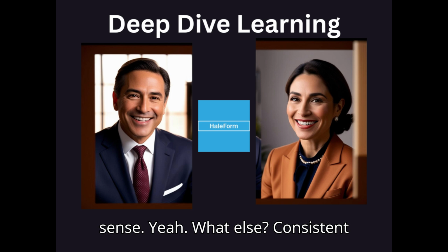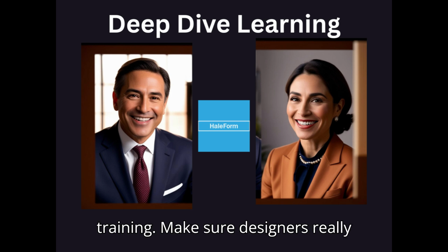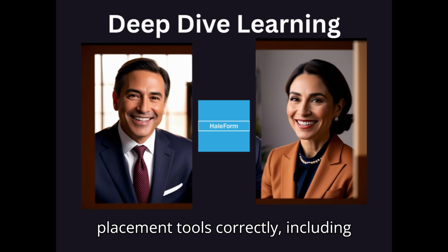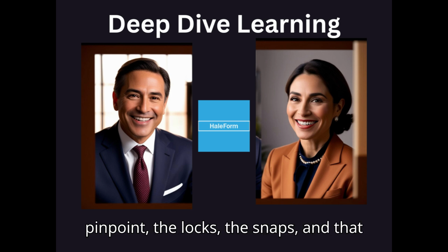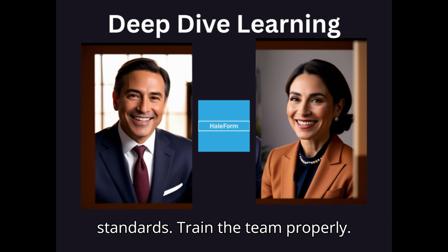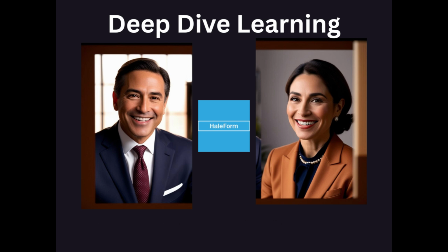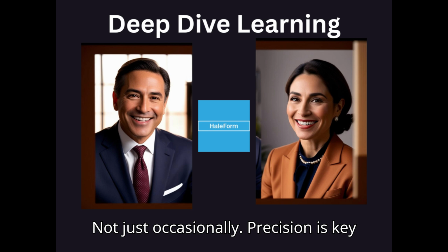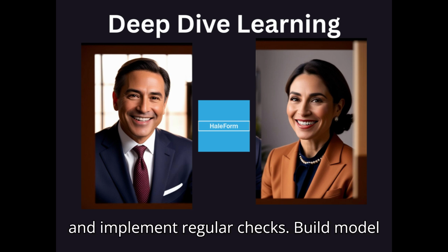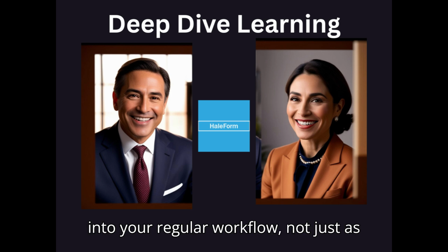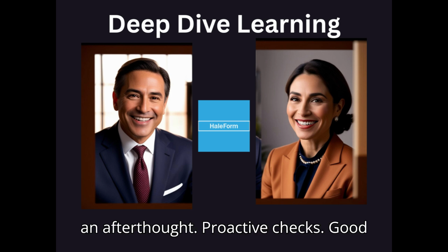Yeah. What else? Consistent training. Make sure designers really understand how to use the S3D support placement tools correctly, including PinPoint, the locks, the snaps, and that they know the project's specific standards. Train the team properly. Emphasize precision, always. Encourage using those snaps and locks routinely, not just occasionally. Precision is key. And implement regular checks. Build model reviews and interference detection runs into your regular workflow, not just as an afterthought.